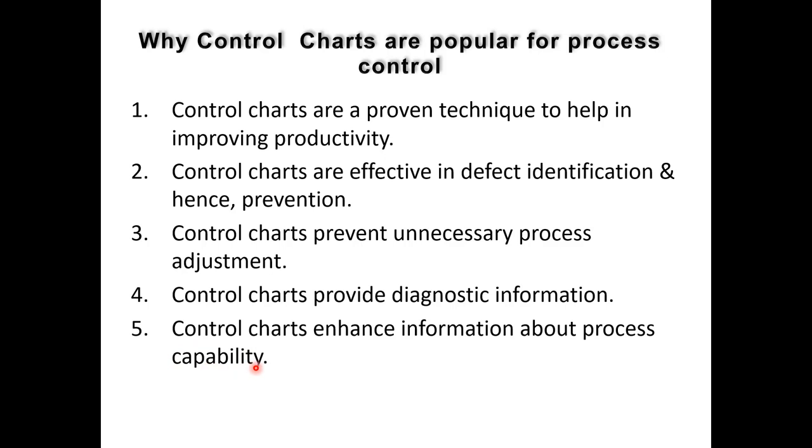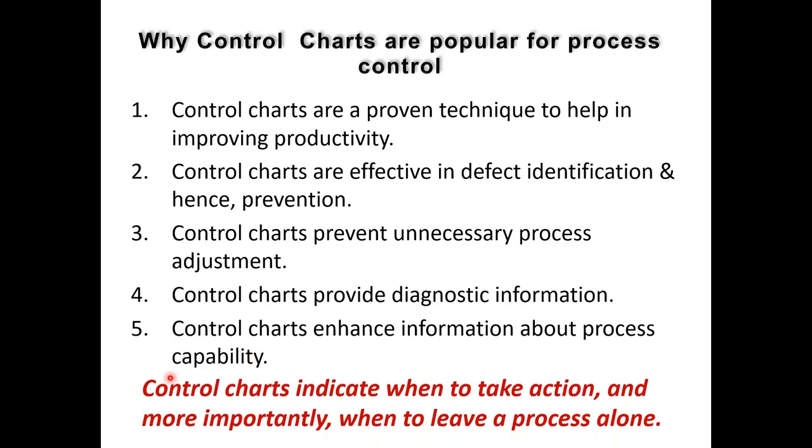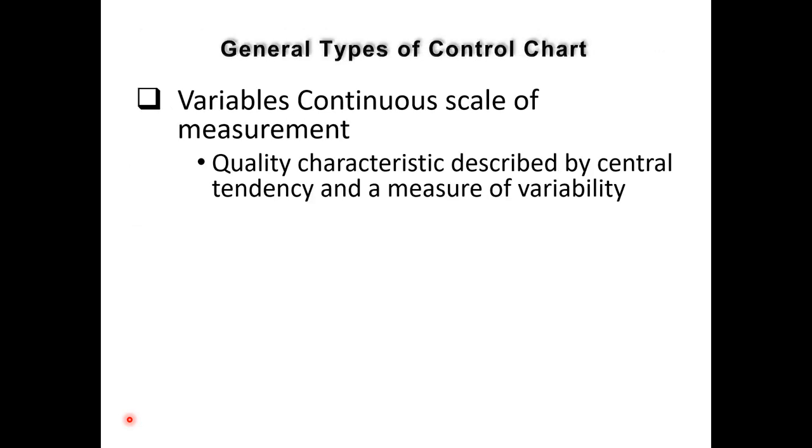But later on, we can have a look at this later on. Don't worry. Okay, right. So control charts indicate when to take action and more importantly when to leave the process alone. So you don't have to worry if it does not give any signal, then you leave the process alone.